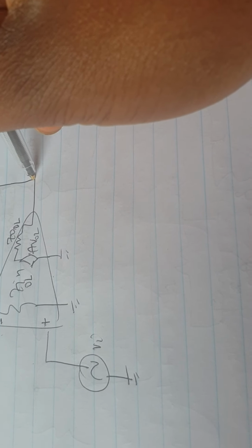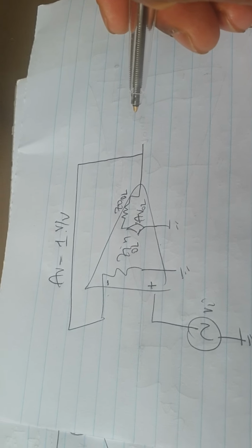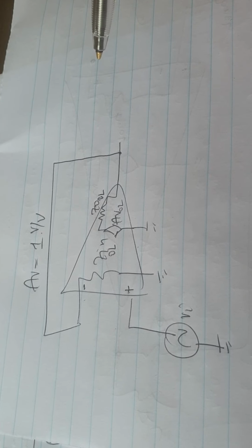With a voltage follower, we have a feedback network that goes from the output. Let's assume the inverting input of the amplifier, the non-inverting input is here, and that way we apply our input signal Vin on the non-inverting input. In the case of the voltage follower, we just have a feedback of 0 ohm from the inverting pin to the output pin of the amplifier. Now, how much overall input impedance do we have? Closed loop input impedance in this case.